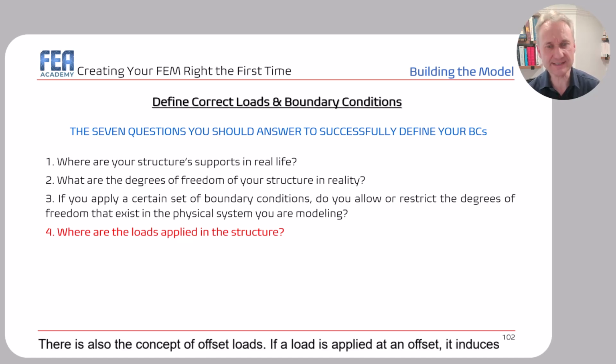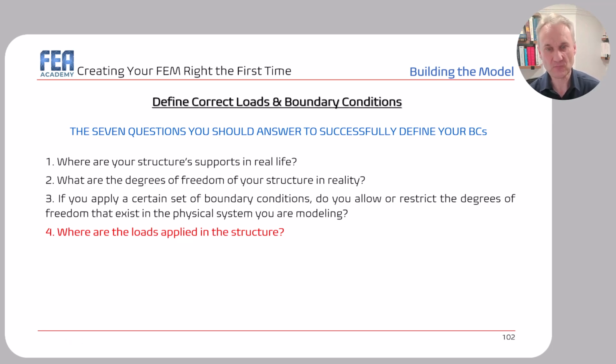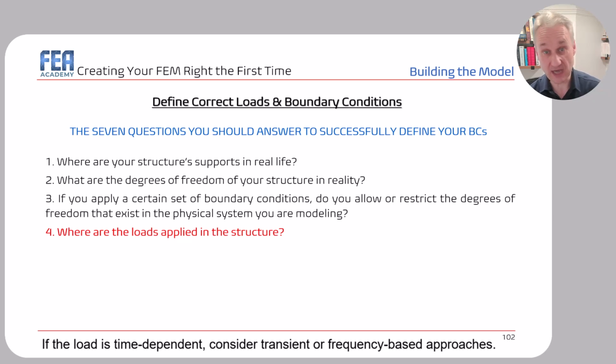There is also the concept of offset loads. If a load is applied at an offset, it induces a moment. This should be included in the model to avoid underestimating stresses. There is also the concept of dynamic loads. If the load is time dependent, consider transient or frequency-based approaches.